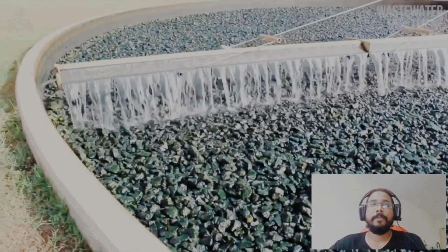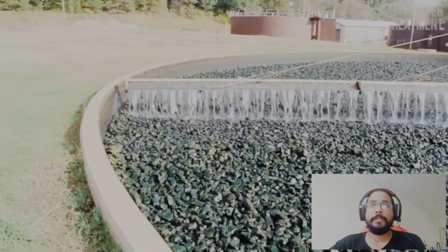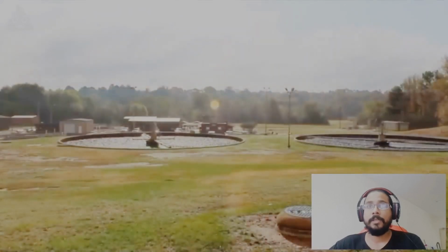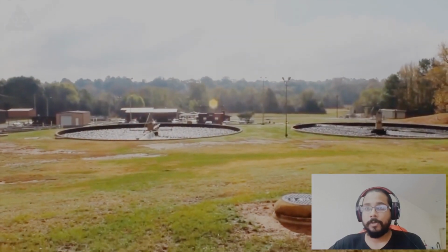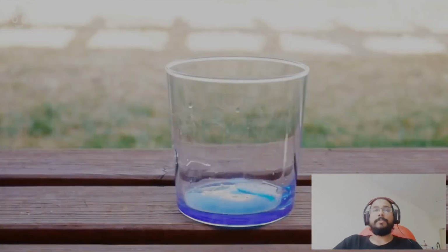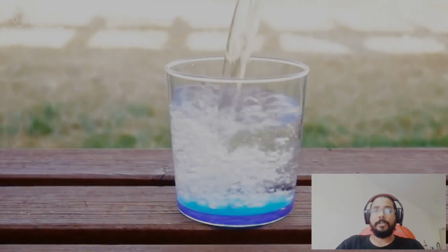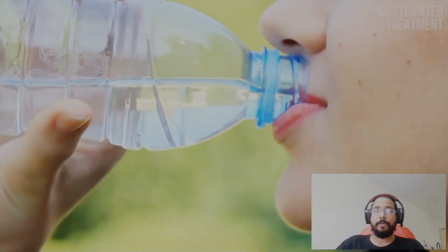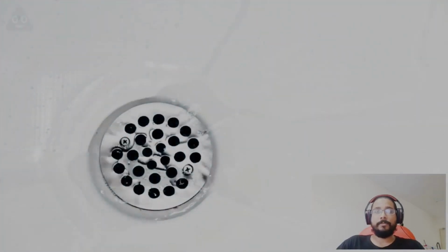the bottom. Step number 5 is filtration, which is removing of the fine suspended solid particles that cannot be removed during the sedimentation process. The final and last step is disinfection, which is done to destroy the pathogens present in the water and make it safe for consumption.